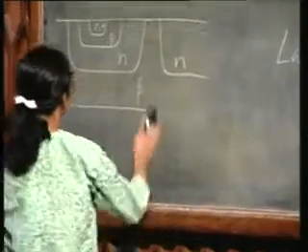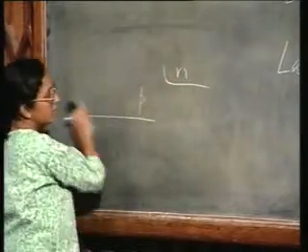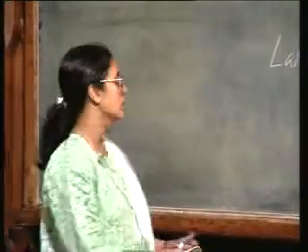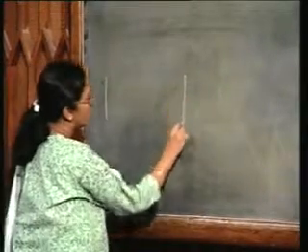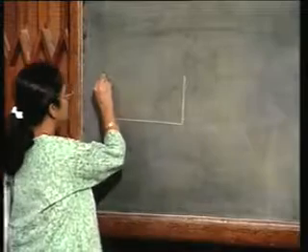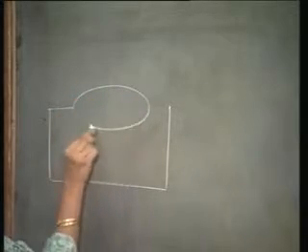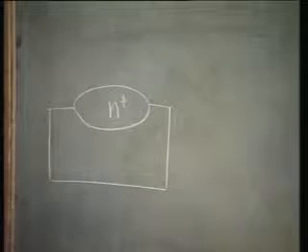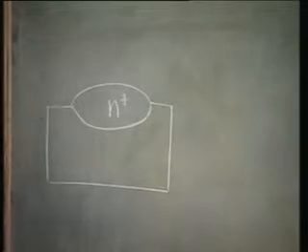The other technique that was used again in junction isolation, the other choice was called collector diffusion isolation, CDI. In this, what you do is you start off as before with the p-type substrate, and then you have the N plus buried layer. Up to this, it is identical to the older bipolar junction transistor technology. The difference is after this.